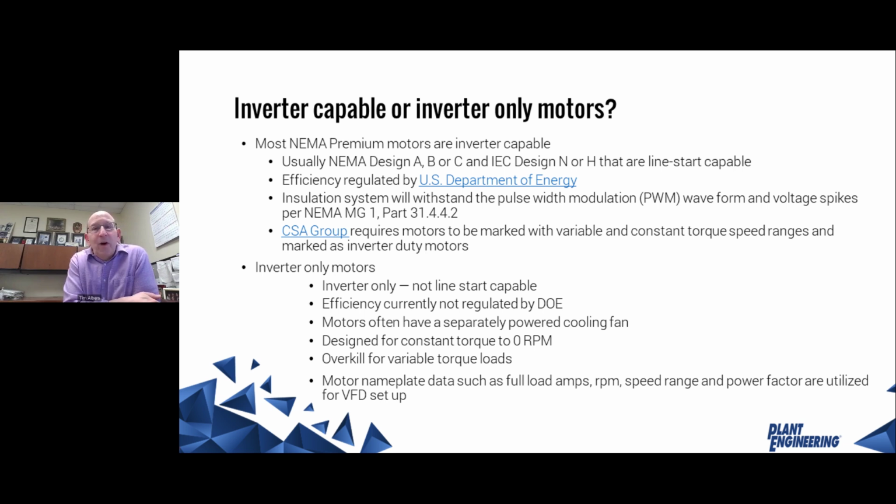The question is going to be, what is the term? There are many, many terms in industry that refer to inverter capable, inverter duty, or inverter rated type motors. There is an industry term that the Department of Energy has started to use, which is called inverter only. And inverter only does mean something specific. It means that it's really not even capable of starting on a sine wave. So if you see an inverter only motor, that's a motor you're going to have to run on a VFD, not really capable of running on sine wave power.